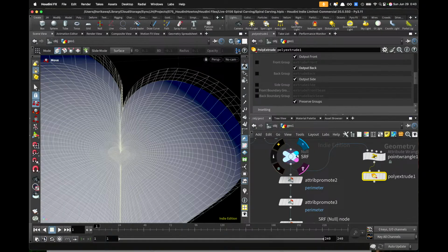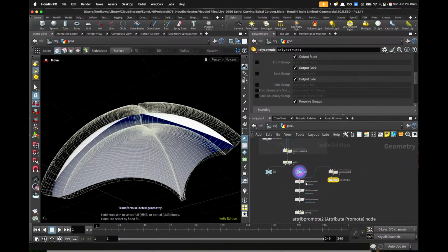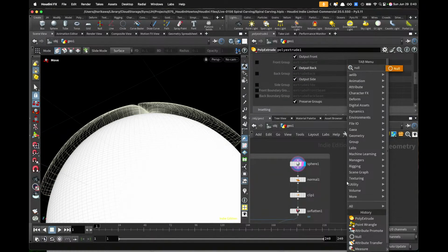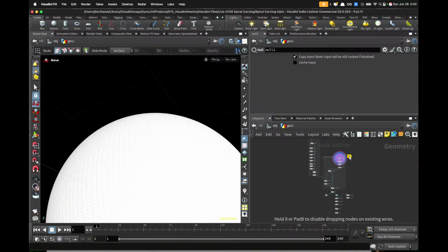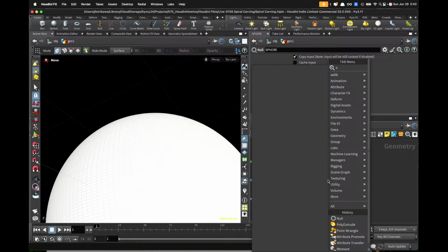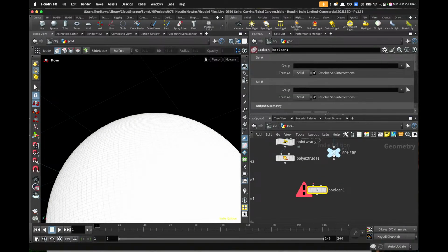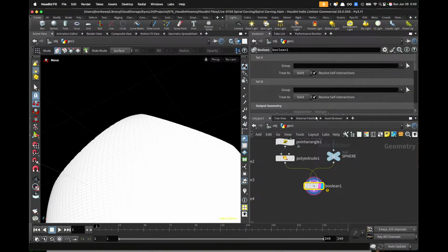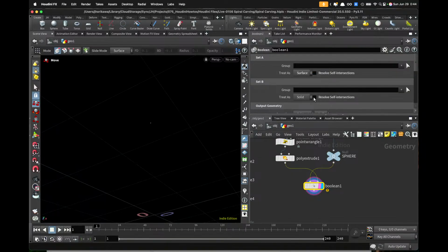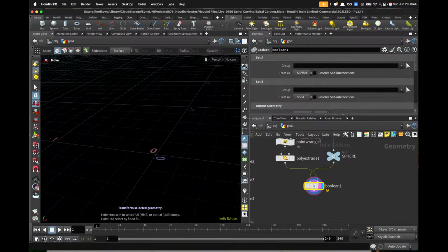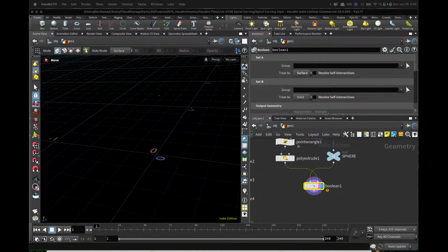And that should be covering the part of the sphere that I want to trim. So let's bring up the sphere and try to create a Boolean. Now the Boolean is kind of unstable, so sometimes it fails. So in order to make sure it's fail safe for many purposes, I need some setup for a Boolean.